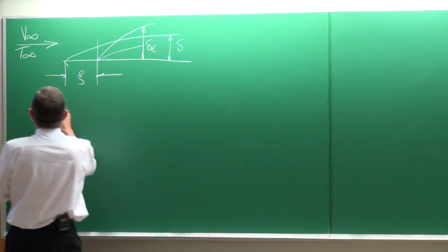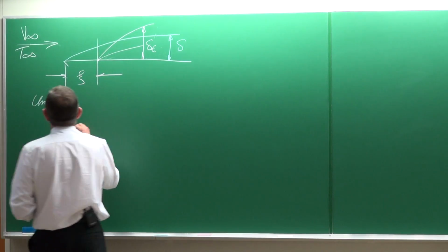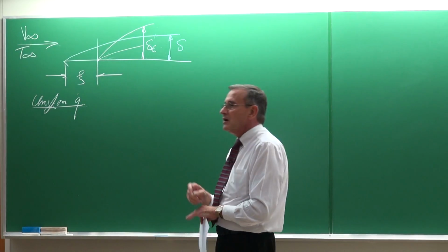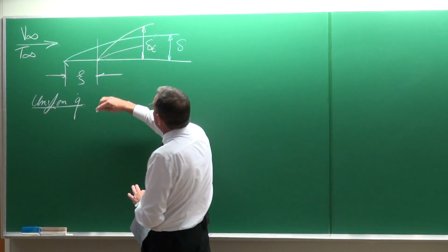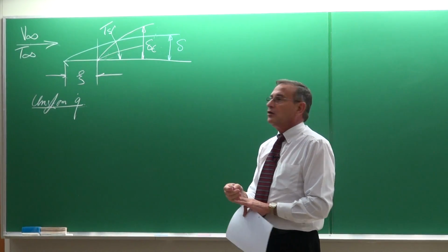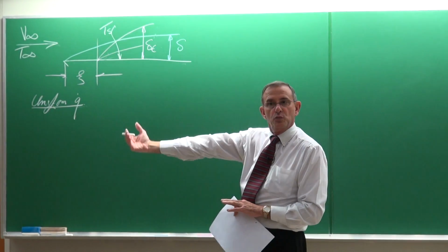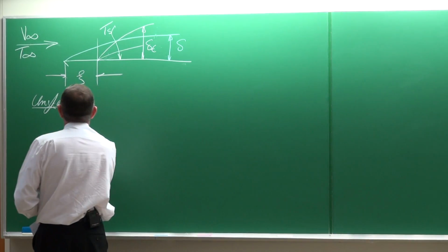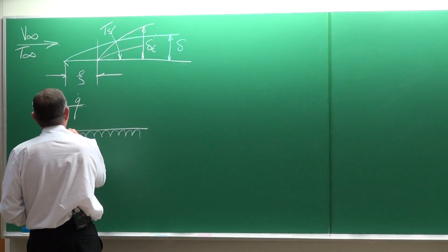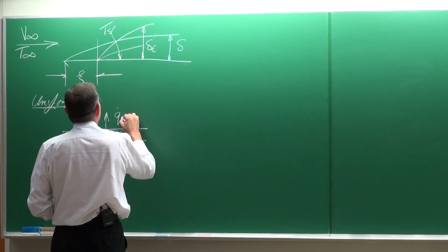And then this part of the flat plate is completed with looking at the cases of having a uniform heat flux on the plate. So with all the work up to this section, this temperature was a constant Ts. The temperature everywhere is Ts, so it is called an isothermal plate. We can also have a case where our plate, inside it there's an electrical heater, for example, which means that the heat flux is constant.